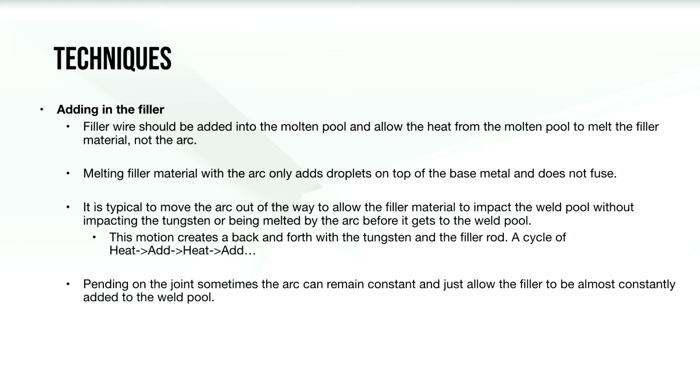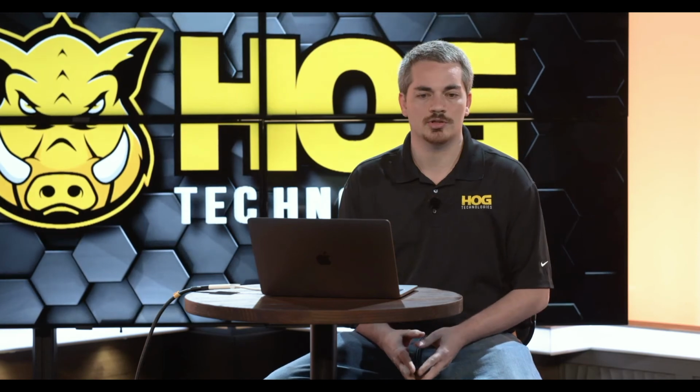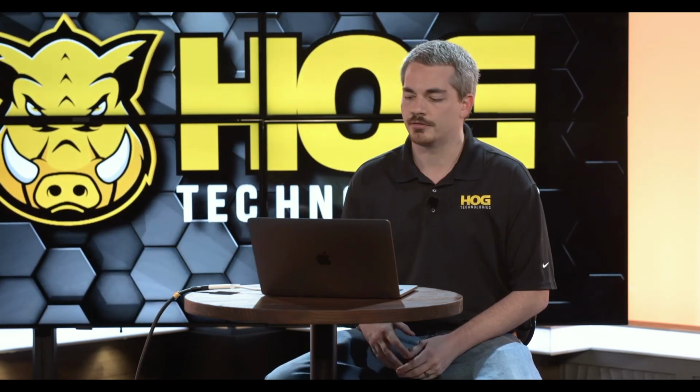Again, depending on the weld joint, sometimes the arc can remain constant and just allow the filler to be added continuously, like when you're doing a straight line draw. So if you've got your arc high up off of the material, you're giving it lots of amperage, and you've got a nice weld pool formed, you can just sit there, hold the torch constant, and keep adding in the filler material as you go along.